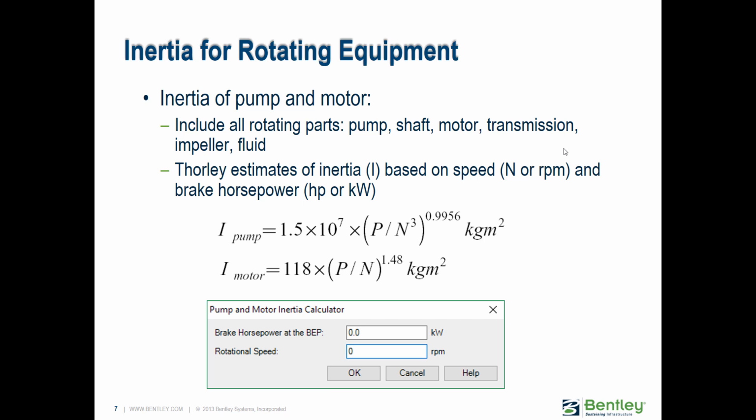You're saying that the electrical supply, the electrical torque, is suddenly stopped. So there's no longer any torque applied to that impeller, but the impeller itself may still take some time to spin down, and that's based on the inertia. So it's very important, especially for a shut after time delay pump event, that you enter the appropriate inertia, because that will definitely affect the transient response to that type of shutdown event.